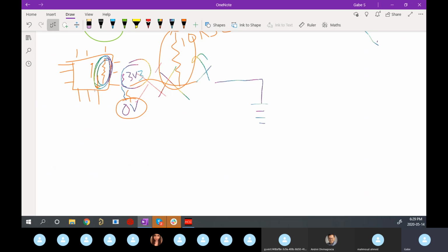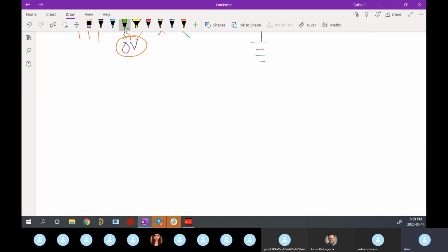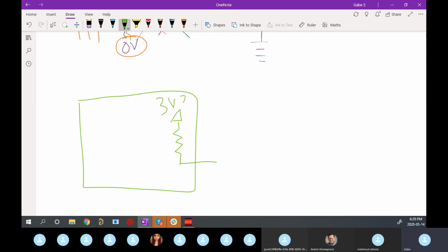If the internal resistor is a pull-up, what happens if you make the mistake of putting an external pull-down? That's an interesting question. Essentially what you're creating is a voltage divider if you do that. You're going to have a fun time if you do that by accident, but let's explore. This is my pin, and I have an internal pull-up, usually pulled up to the logic level of the chip. Let's say our logic level is 3.3 volts, and this little box is the microcontroller chip.